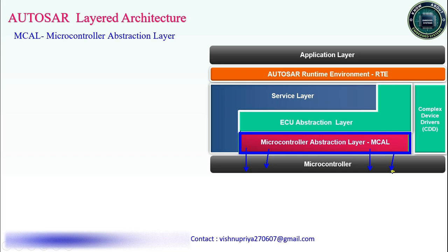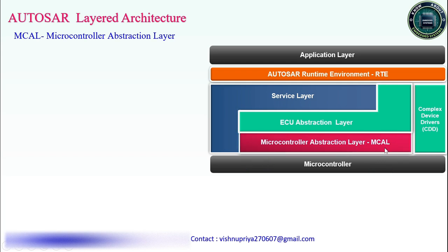Only this layer is dependent on the microcontroller, and all the rest of the layers, application, RTE, service layer, and CDD, are not dependent on hardware. Only the MCAL layer depends on the hardware. So we have to develop different driver programming for your MCAL with respect to your microcontroller. According to the microcontroller design, we have to develop the software for the drivers in the MCAL layer.